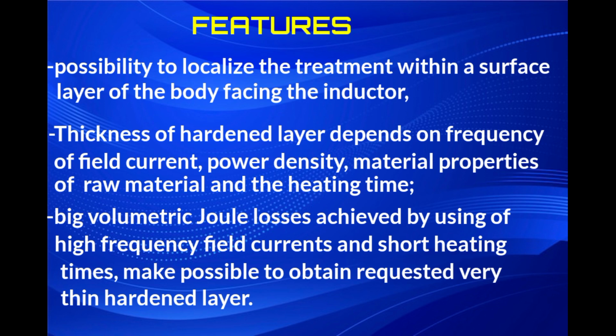So now we will talk about the features of this induction surface hardening process. First, it is possible to localize the treatment within a surface layer of the body facing the inductor. Second one, the thickness of the hardened layer depends on the frequency of field current, power density, material properties of the raw material, and the heating time.